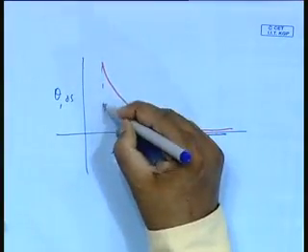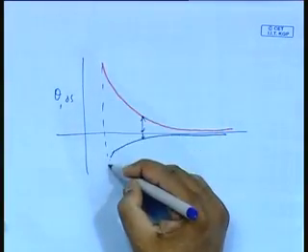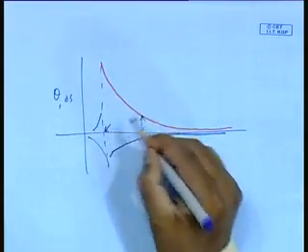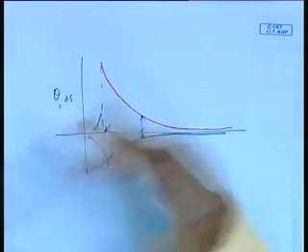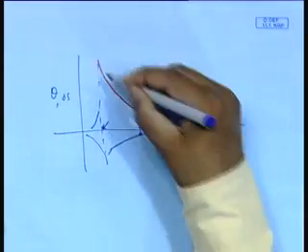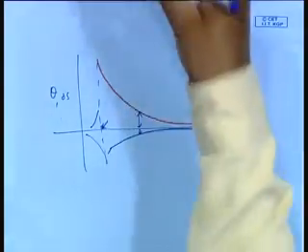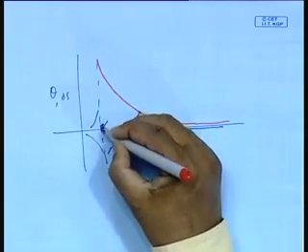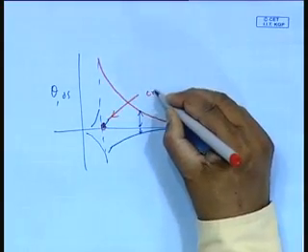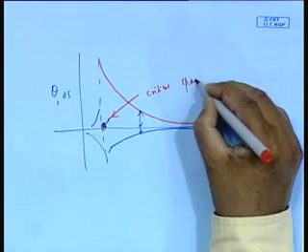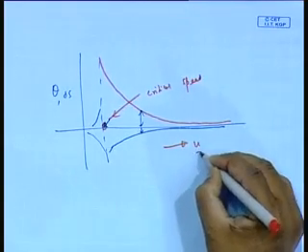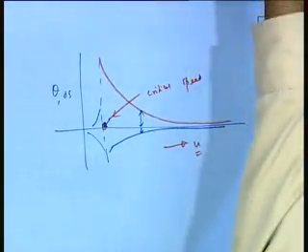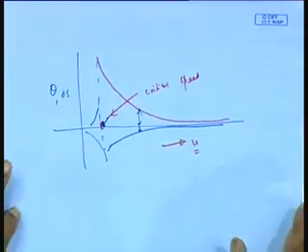Now at this speed, suddenly it changes to the opposite direction. What is that? This is the critical speed, the speed where the reversal happens. At this point things become singular, very large rudder angle is needed. So this point is what is called my critical speed. Anyhow, I will just close it, eventually, on the submarine part.